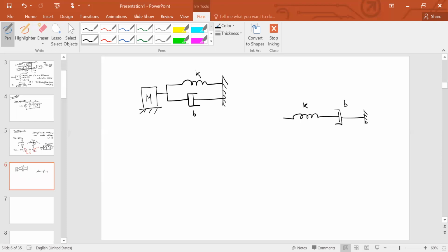It turns out that you can treat this like an equivalent impedance. All that you need to be mindful of is the through variable and the across variable. Suppose there is a connection like this, a contraption built with a spring and a dashpot. Suppose the spring is displaced by x1 and the dashpot is displaced by x2. Because the force is a through variable, here is where the physical insight plays a big role, you would know that F is equal to kx1, that's equation 1.